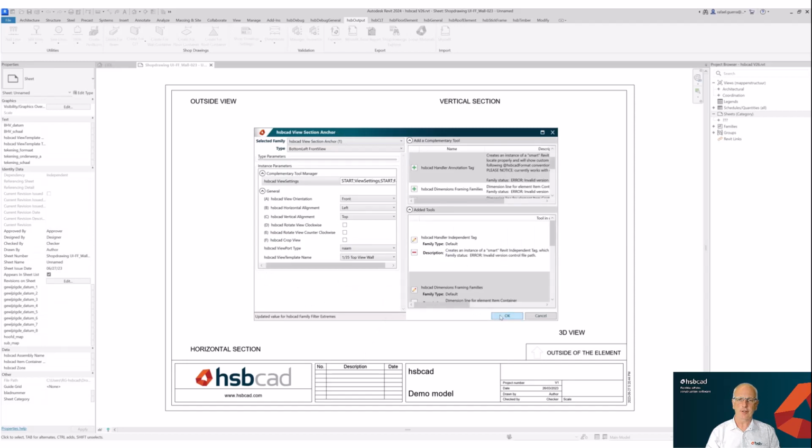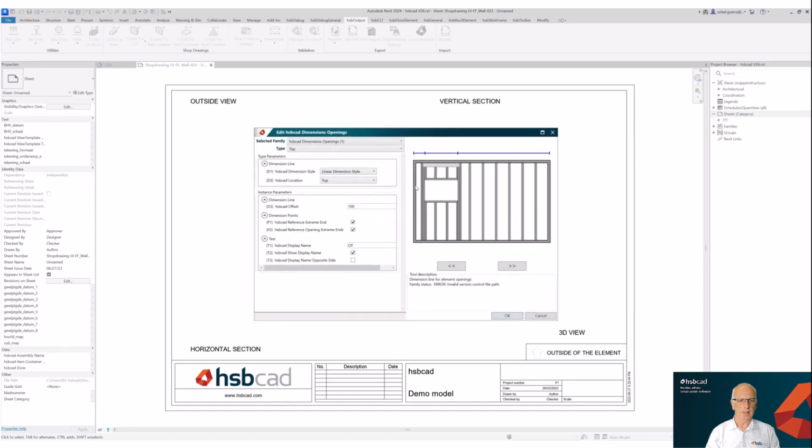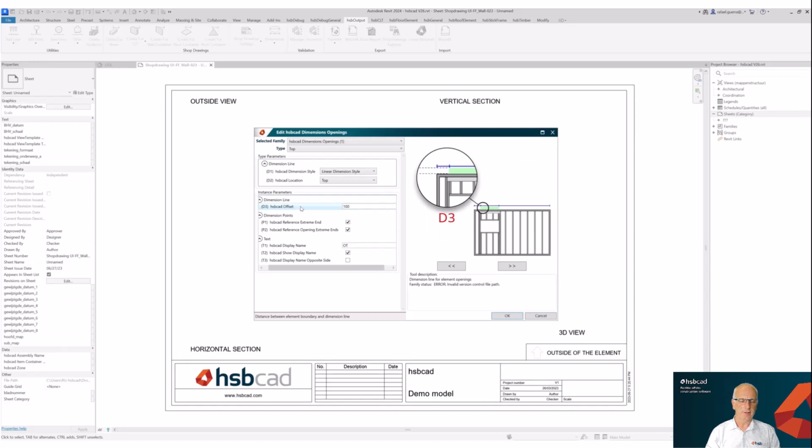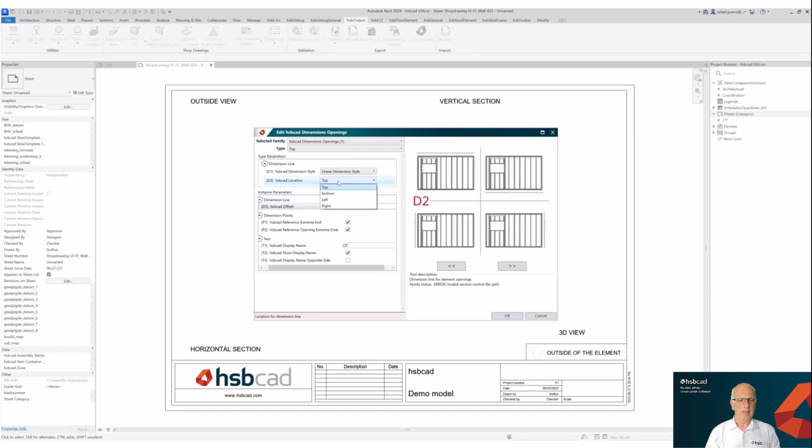And then you just continue working your way down, and one area that we didn't cover yet, for example, would be opening. So you would then select your openings and you determine how you want your opening to be. And again, you can have the location of your opening line on the top, the bottom, the left, or the right. And in determining that, you can determine also what the offset value might be for this particular opening and be able to set the equivalent values in each case.